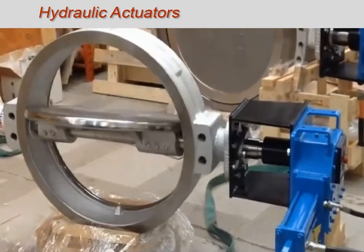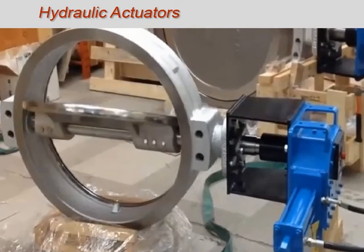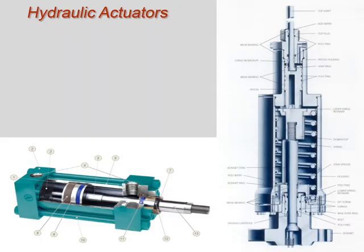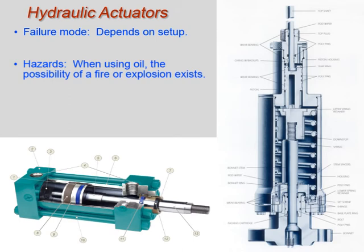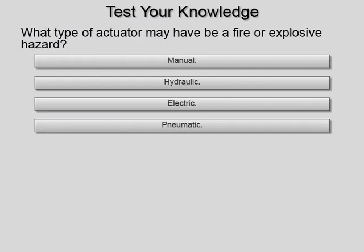They are often used in power plants operating massive equipment. Hydraulics is rarely used in LWO facilities. The failure mode of a hydraulic actuator depends on the valve design and setup. When using oil as a medium, leaks can cause the oil to aerosolize, making it a potential fire or explosion hazard, which is why it is rarely used in our facilities. Hydraulics can be used to develop large amounts of torque to operate large valves.